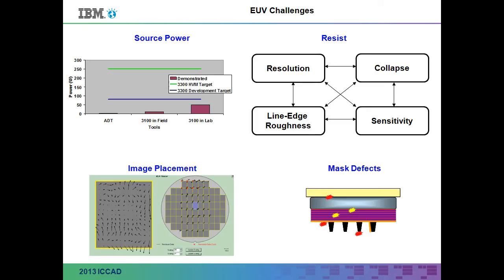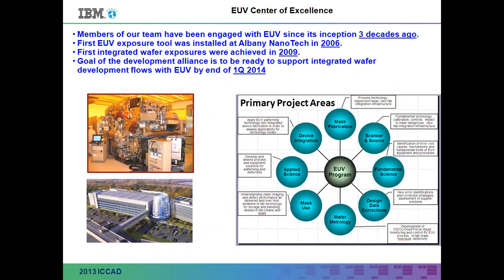There's no protective film. In optical lithography, we have sort of a piece of saran wrap that sits above this mask that we call a pellicle, which defects land on, but they're outside the focal plane, so they don't matter. We can tolerate that pellicle getting quite dirty. Here, everything lands directly on the mask and is a problem. So all of that is being addressed in the industry.